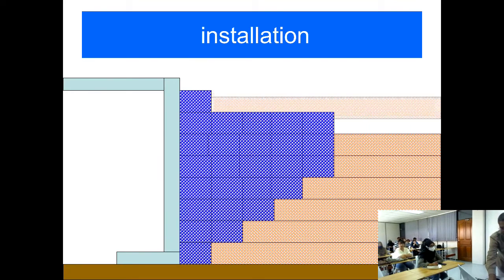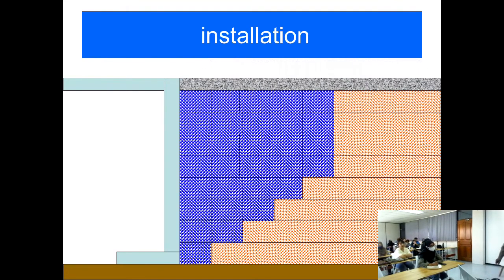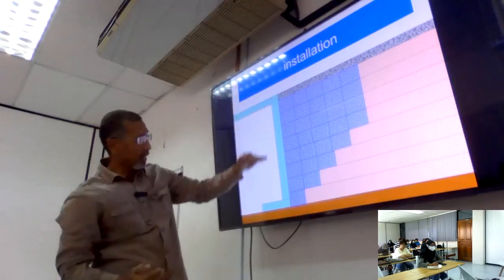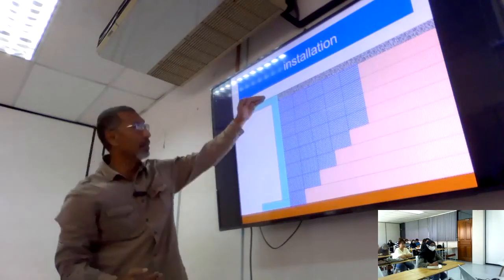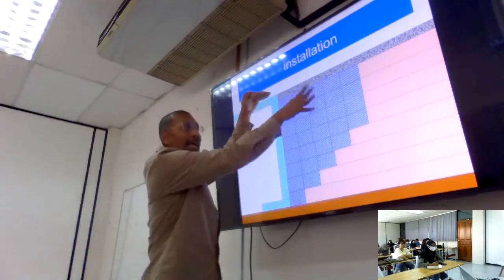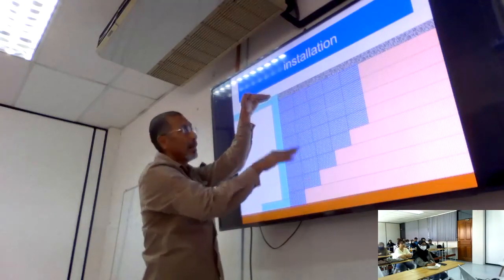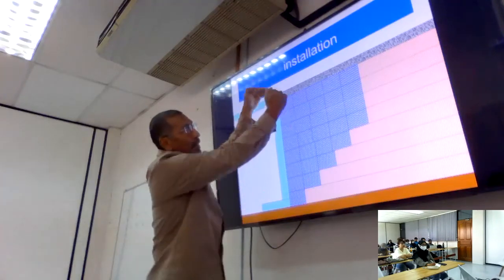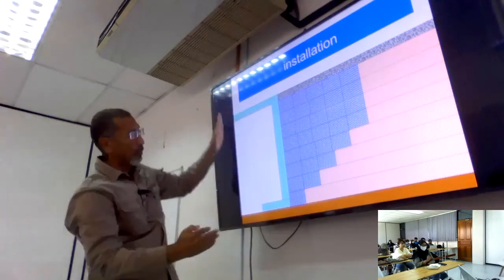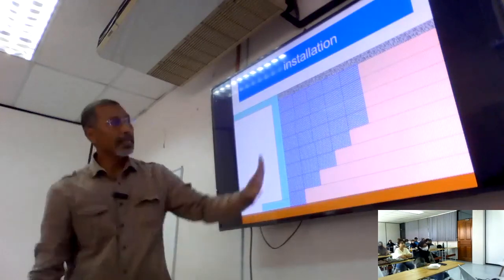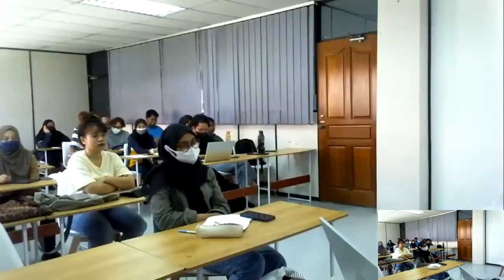So that will prevent this area from settling, that prevents differential settlement. For example, this is a bridge or culvert or retaining wall. This lighter material will prevent the soil below from settling, right? Then we don't want a gap between this place and this bridge here, which will not settle because it is sitting on a pile. So that's how we place them behind a wall or bridge abutment.